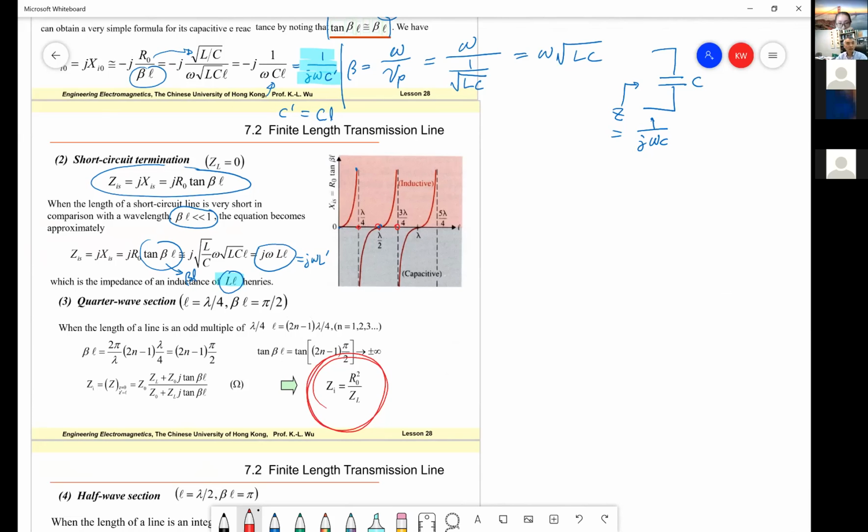This is easily derived from the property of trigonometric functions, okay? So that means the impedance reverses, multiplied by this square, which is the characteristic impedance squared. But if we divide by Z0, I define this with a small letter.